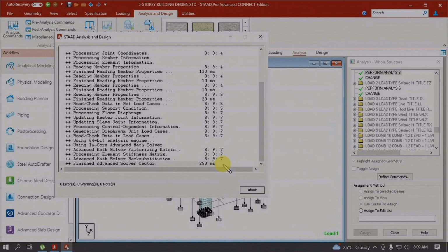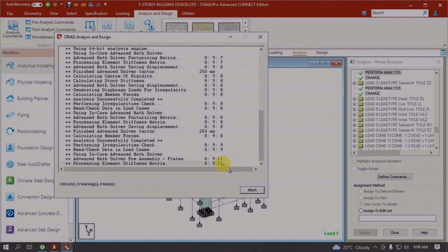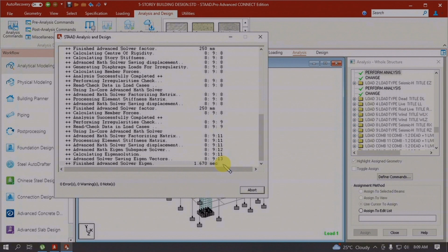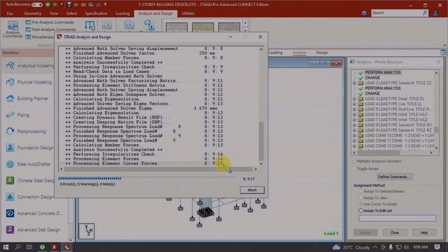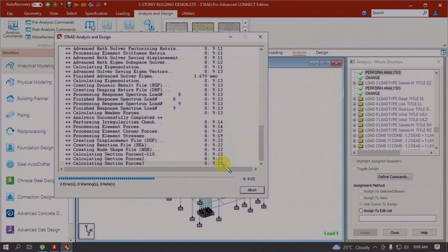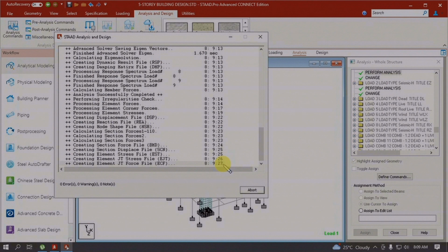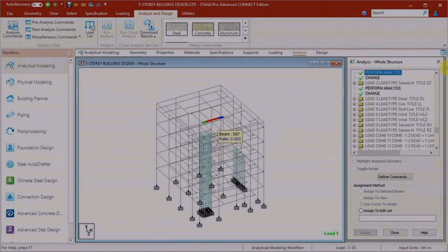After analysis has been run, we go to output and check any changes in base shear and do the scaling again, just like we did a while ago. And don't forget either to check the participation factor, for it must always be at least 90% in both X and Y directions. If there are no noticeable changes, then proceed to RCDC again.